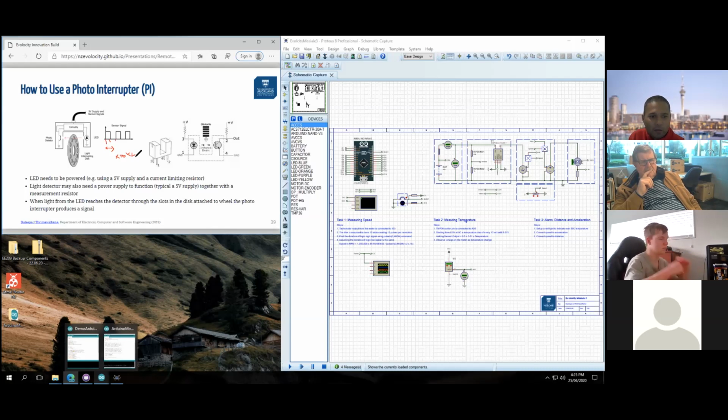So the whole idea about a tachometer is either counting the number of pulses or working out the duration of a pulse, for example, how long it was high, or logic 1, and from that predict how long the wheel spent to complete one whole revolution. And if you know how long it took to complete one revolution, then you can work out the speed quite easily. Does it clarify how it works?